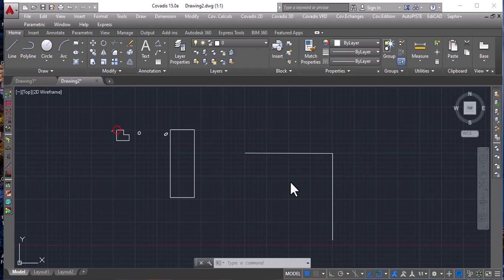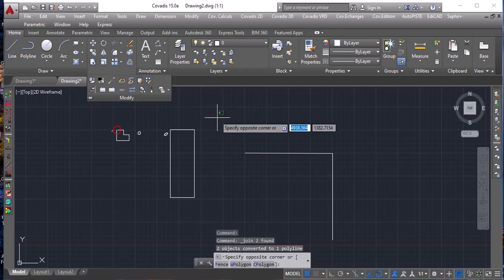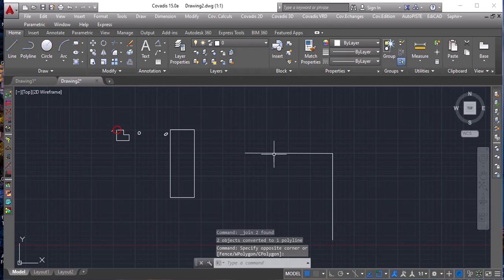Okay, now let's go to explode. Just now I wanted to decompose this polyline. After showing you this, I wanted to show you a different method from the one we have just seen, the break method. Now we are going to see the explode method. This is one single line. We are going to decompose it into two different line segments. So we select the command explode, then we right click and press enter. Now we see we have this line segment and we have this line segment.